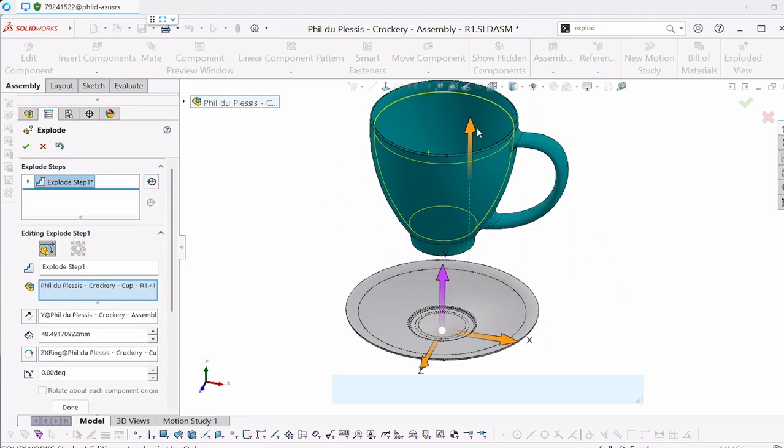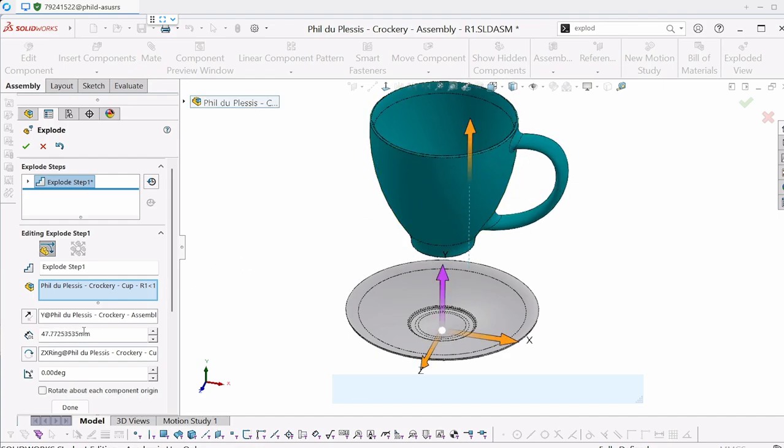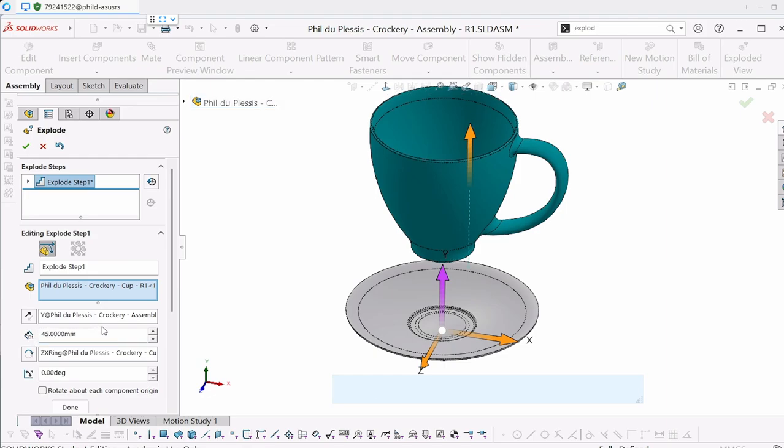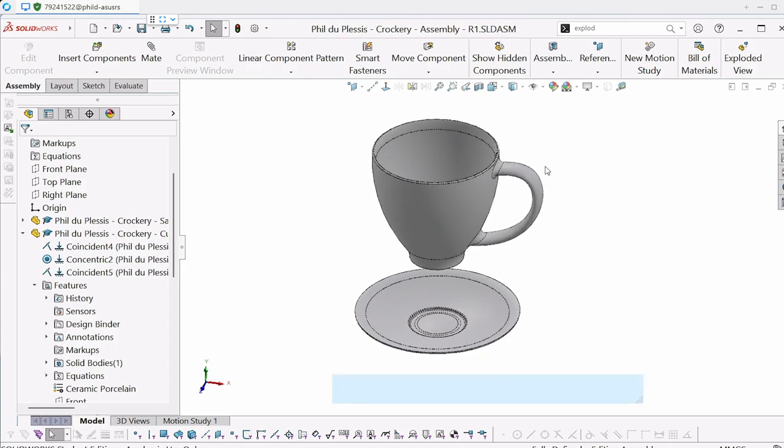And in this case, there's no, I mean, it says drag. You can kind of see where you're going, but it's not really snapping. You'll see in the properties manager here that's 47 millimeters. If you want to round it off, you don't need to, but I'm just showing you how to do it. That's at 47. Okay, and I'll say all right. And that's it. Then you say Control Save, obviously.